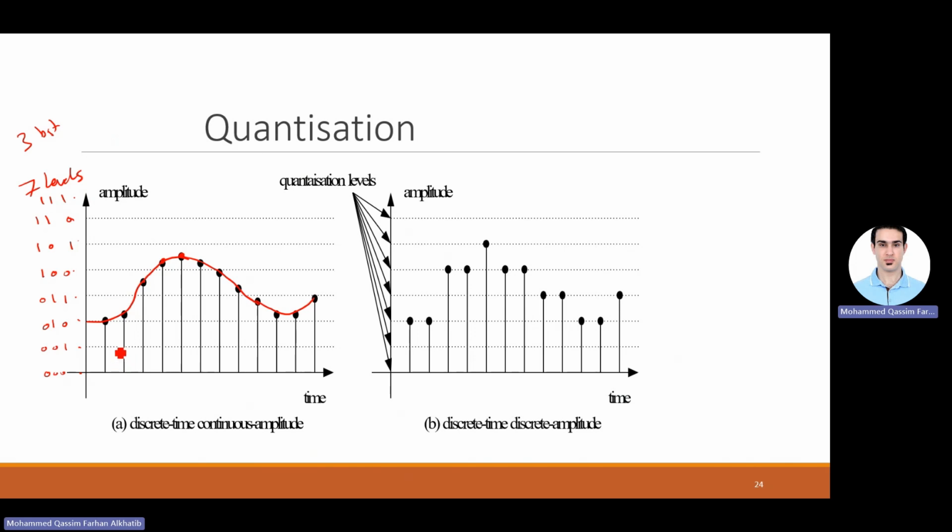All right, so that's the sampling. Quantization means that I can have quantities from these levels only. So for example, go to this sample, that's exactly at 0, 1, 0. This one, is it closer to 0, 1, 1 or 0, 1, 0? This level here, so this will be approximated like this one. This one here, you can debate here or there. Let's say it's going to be here. This one is closer to this level, so it is approximated here. Now notice my exact values are gone. I have approximations to the nearest level.